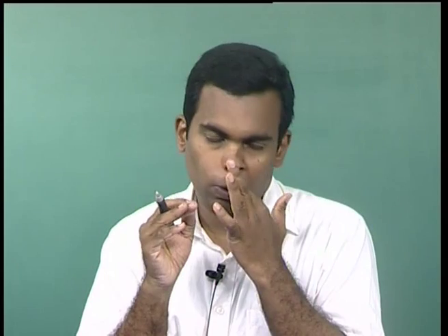Likewise, when the Reynolds number is very large, of the order of thousands, we can hope that the inertial forces in the fluid must be dominant compared to viscous forces, and therefore, we must be able to get a suitable approximation by neglecting viscous forces altogether. So, it seems like a reasonable proposition, and that is what we will do to begin with.